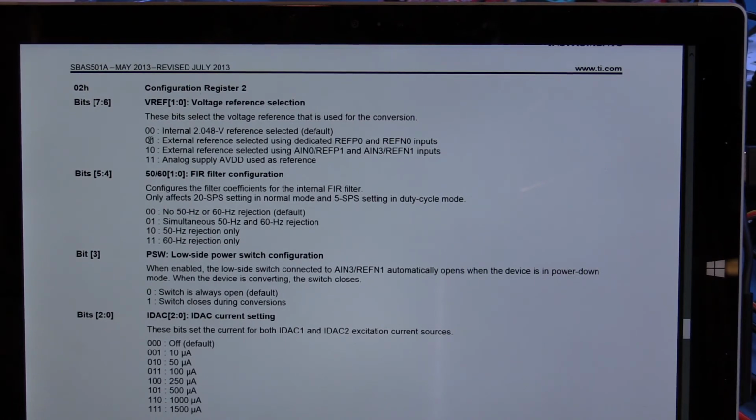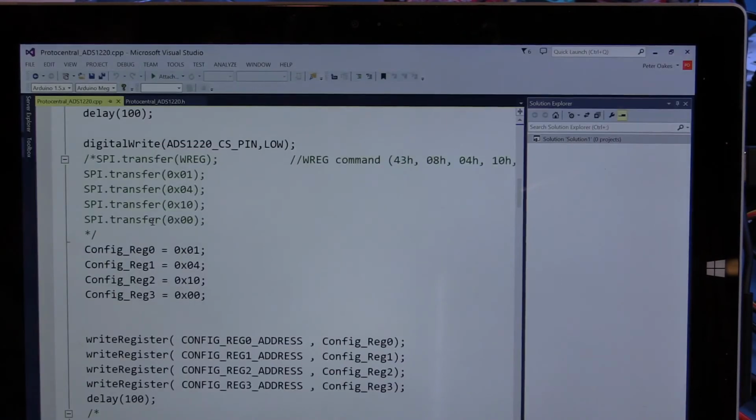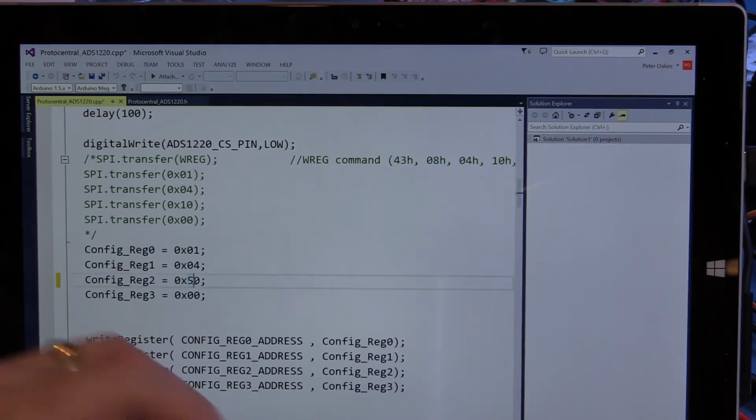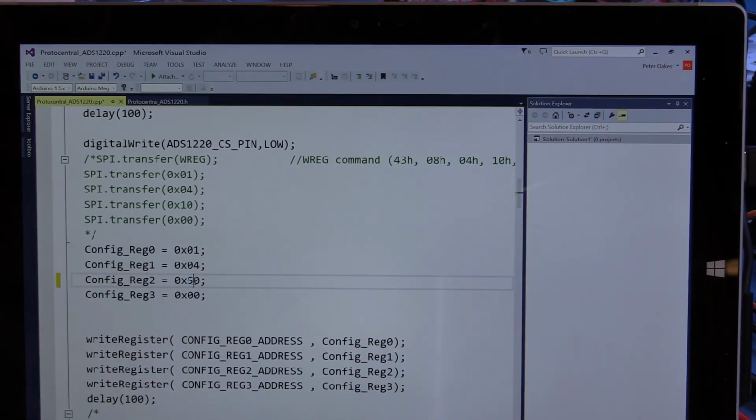So it looks like we want to have 40 hex added to whatever value we're currently putting out. So we would probably want to put out 41 hex on that byte there. Sorry, not 41, that's 1, 2, 4. Yeah, sorry, 50. We're adding 40 to it, and we've already got a 10 there. So we want to change this here, which is 10. We want to add a 40 to that, so we'll make that a 50 hex, which is the 40 hex and the 10 hex, and save that.